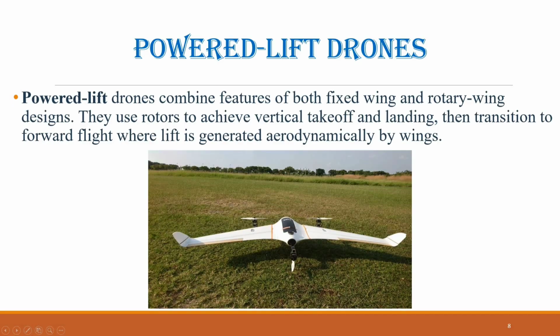Powered lift drones. Powered lift drones combine features of both fixed-wing and rotary wing designs. They use rotors to achieve vertical takeoff and landing, then transition to forward flight where lift is generated aerodynamically by wings. This hybrid approach allows powered lift drones to operate in confined spaces like rotary drones, while also achieving the efficiency and range of fixed-wing aircraft.